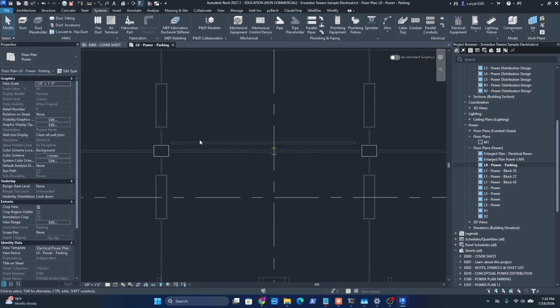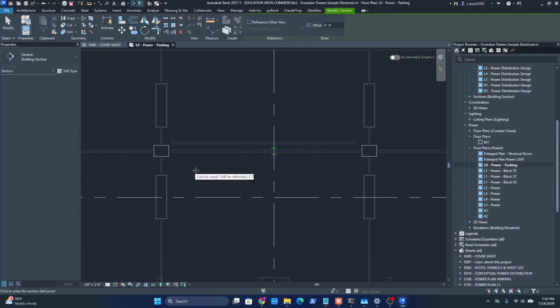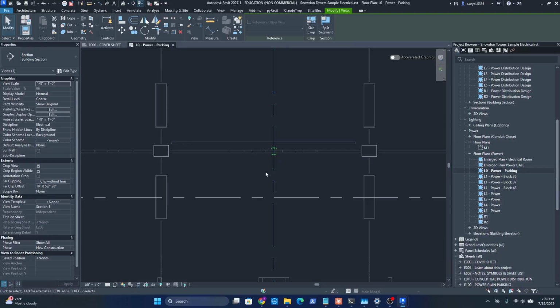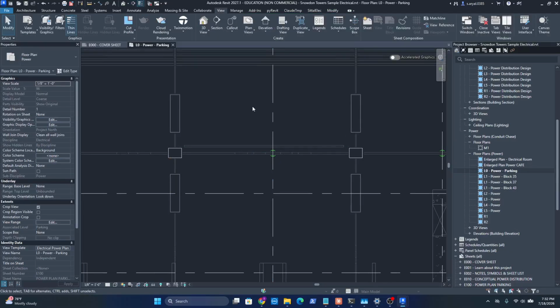The point is this: the conduit has to bend, otherwise it runs straight into the structure, or into the other pipes. The usual way to handle this is to draw a section view, look at the conduit from the side, find the clash, and adjust it by hand. What I've done instead is build a small pyRevit script that reroutes the conduit for me.